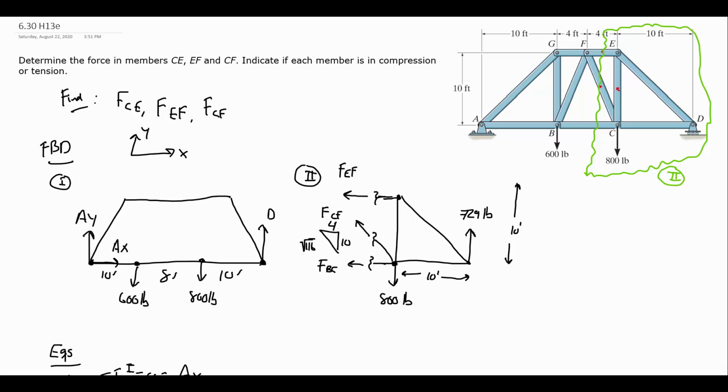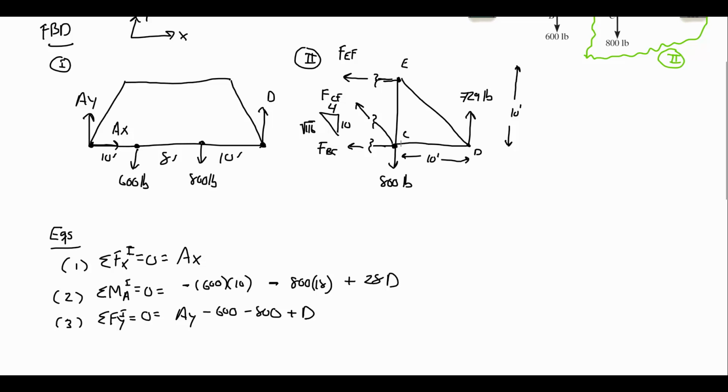And finally, I'll just copy down some of the points. All right, so picture 2, the section cut is now complete. And if we look, I've introduced 3 new unknowns in the section cut picture, which are going to be those internal forces in the 3 beams that I cut through. So picture 2 is going to give me new equations to create.